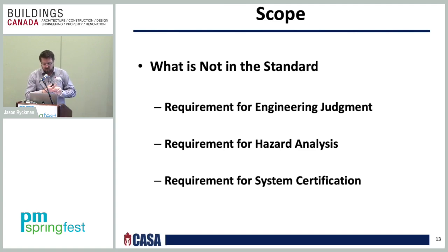And as to a process to determine that the system is functioning, in order to manage the cost of inspection while providing a reasonable degree of protection, NFPA 25 assumes that if no changes were made to the building or the hazard, and the original installation was accepted by the applicable authority having jurisdiction, then it would still be considered acceptable, okay?